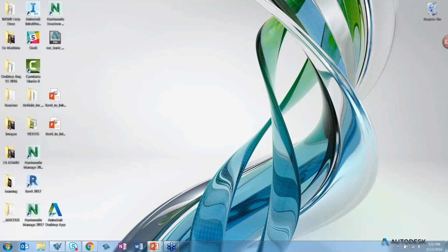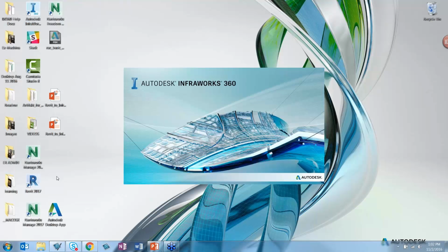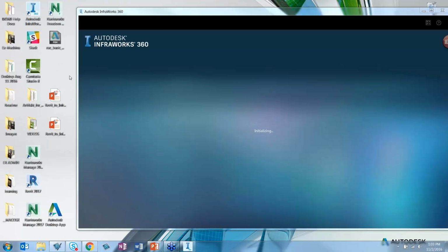So there are some options. If you can figure out the offsets from the project base point so you don't have to change it like I did, then you could add those offsets in there. The process that I showed was a simple bring it in, no fuss. When it comes in, it's processed in the right area rather than trying to figure out negatives and positives and meters and millimeters and things like that. So you certainly can. It's going to take a little bit of trial and error to do that. So you have those options.